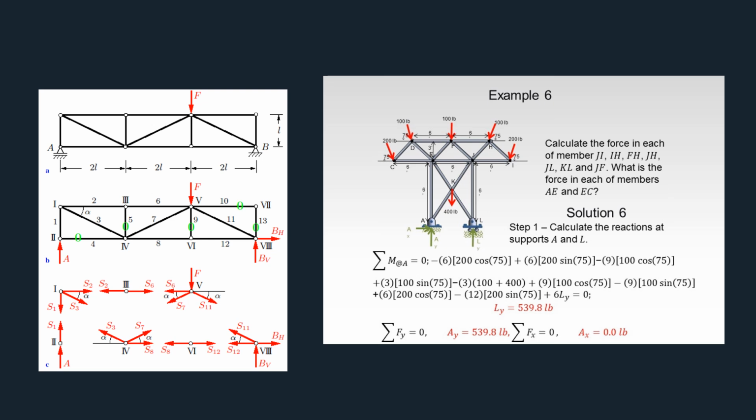As you can see in example 6, there are the 3 equilibrium equations that they use, making sure that they all equal 0, and the forces acting on each joint are either going up from the side or down, depending on the force. If you look at the second photo over here, you can see where they highlight certain parts where there could be tension or compression, depending. They use vectors, or it could be scalars, to show where these forces could be going.